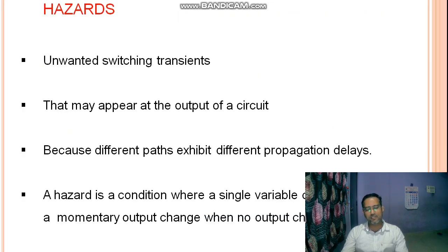Hazards definitions. What is a hazard? A hazard is an unwanted switching transition. What is an unwanted switching transition? It may appear at the output of a circuit because the different paths exhibit different propagation delays.